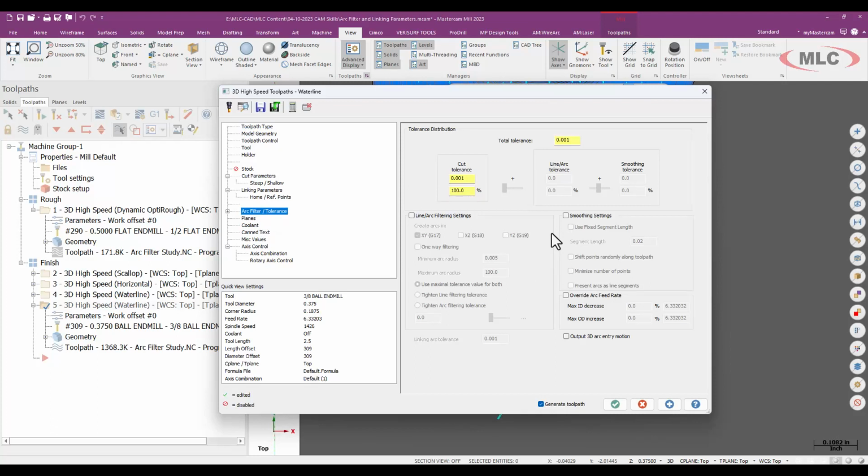So I'm going to do this in much the same way, with the exception that for a finished toolpath, I might bring in some smoothing settings to help even out some of those passes a little bit. This isn't always necessarily going to make my toolpath smaller. It typically does, but sometimes applying a heavy smoothing element can blow it up a little bit. So you do have to be aware of that if file size is a concern. But generally speaking, it will make it smaller overall. Right now, this water line's at about 13K or so in NCI data, so it's a pretty big toolpath.